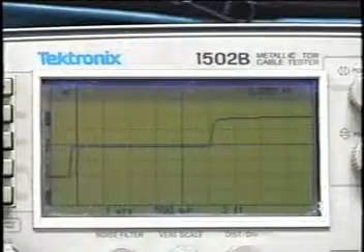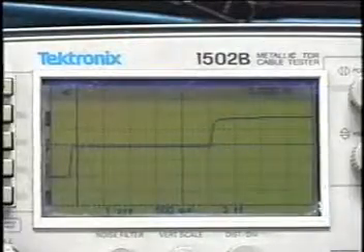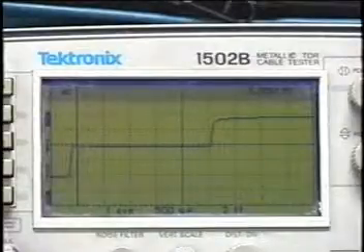The time domain reflectometer, or TDR, is used to test for faults which cause impedance mismatches in aircraft coaxial cables. Any impedance mismatch between the transmitter, the antenna, and the cable is cause for loss of transmission power. The TDR operates by sending a test signal through the length of the cable, and faults such as shorts or opens are reflected back to the TDR.